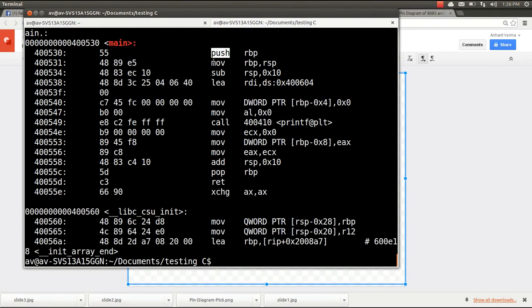These are known as mnemonics. These are the instructions that we give while writing in assembly language. An individual code instruction, for example move, is called an opcode, and a hex code associated with it is 89. So move and 89 are essentially the same. 89 is a hex code that the computer understands so that it executes the move command. What it is essentially doing is transferring the data from the accumulator register into the counter register. So this is how the assembly language and the assembly code look.